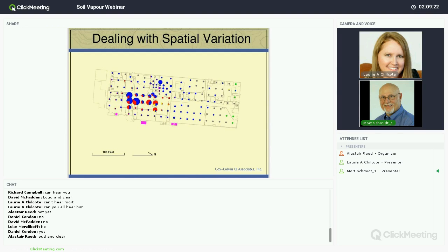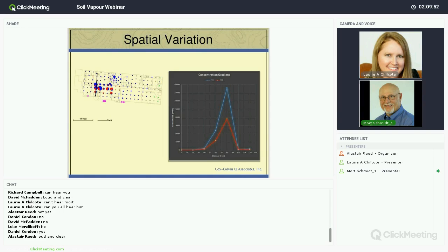What we found then, and have found repeatedly since, is that when you do a soil gas survey, the contamination more often corresponds to where the back door was in 1950, because people disposed of solvents very differently then than they do now. And nobody even remembers that. In 1950, I wasn't even born yet, and nobody's going to remember how that got there. We figured this out on the basis of aerial photos, et cetera. Yeah, that used to be the back door, but you wouldn't know to look there probably. And so you need to collect a lot of samples.